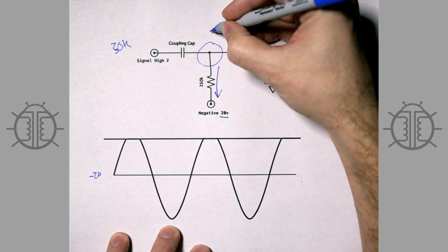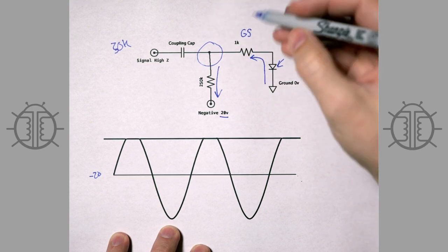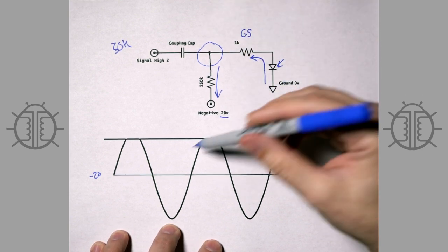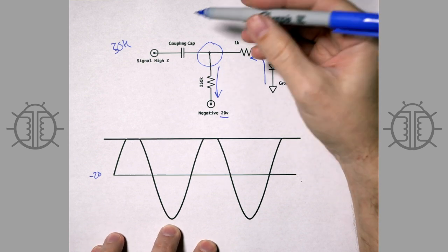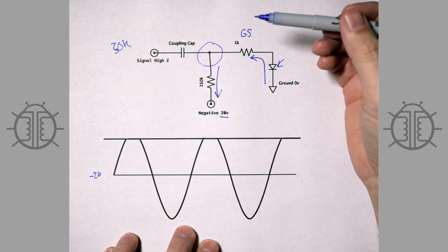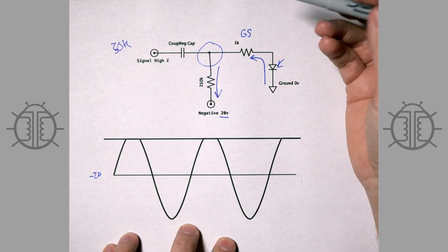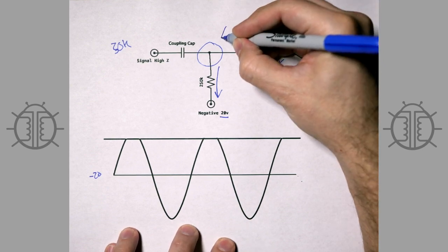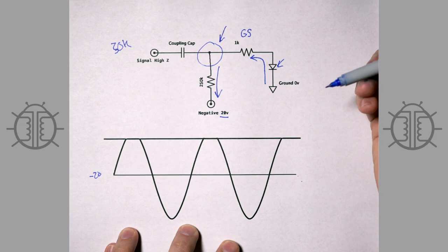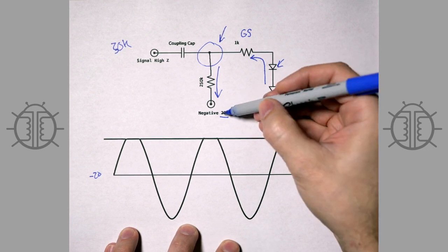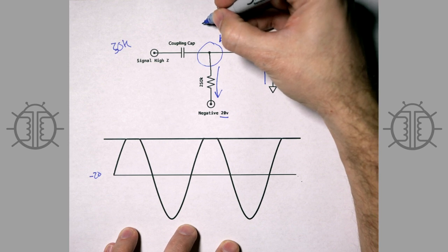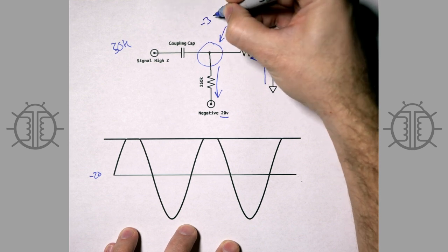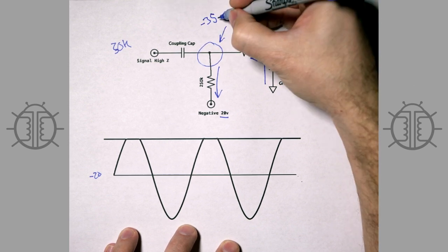And so if you actually take an output stage that's suffering from this, which is most AB1 capacitively coupled fixed bias output stages suffer from this, and you put your meter here and you clip your amp, I've seen these drop 15 volts very quickly. So you might get negative 35 or more volts here.